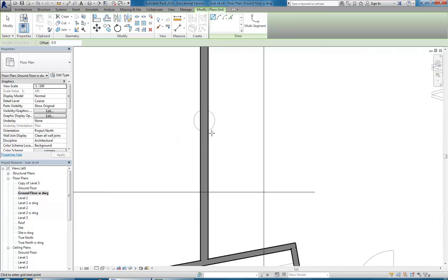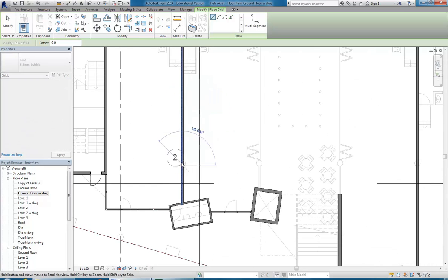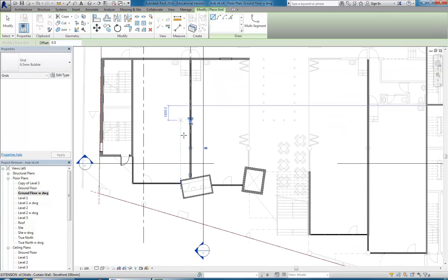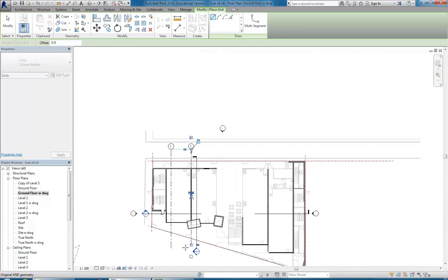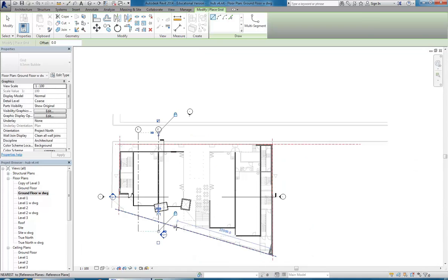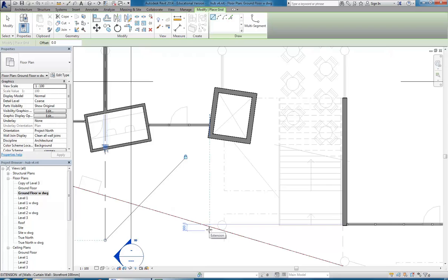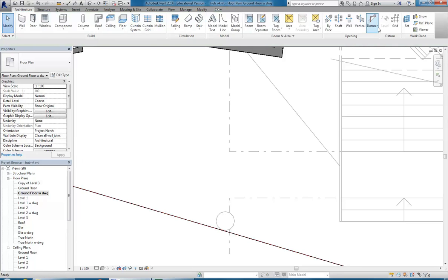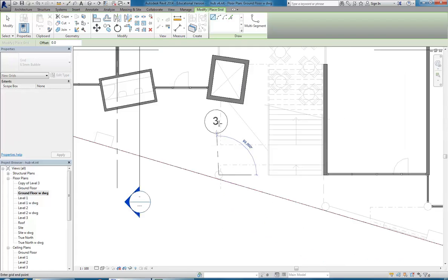And so I've got another column here. So again, SC. You might not need to snap to the centre, but you need to know where the grid line would be drawn. Notice I'm just stretching the ends so that later on they're easier to select. Okay, so here it's being difficult, so I'll just start again. Grid, SC, and there we are.